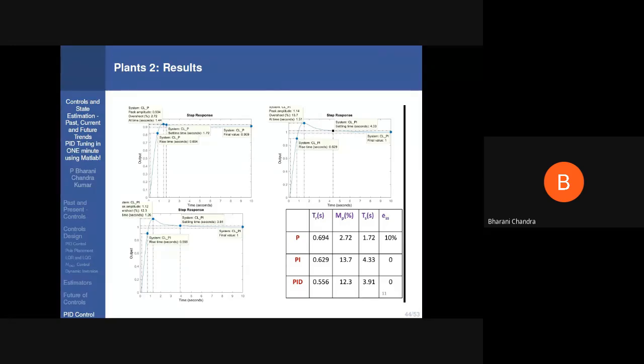And I think all the researchers who want to work with fundamental control, who have just started control system design, or who are experts in control system design as well, should be aware of this standard auto tuning method. By using it, in one minute one can get the KP, KI, KD values. The so-called Ziegler-Nichols tuning method is fine. There are also methods you might have come across in papers, like the bacteria foraging method for PID controller tuning or particle swarm optimization, and so on. So there are hundreds of methods.